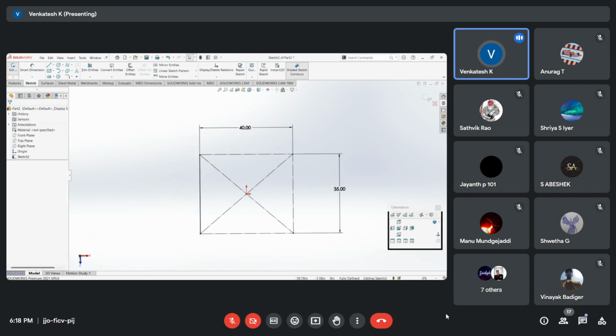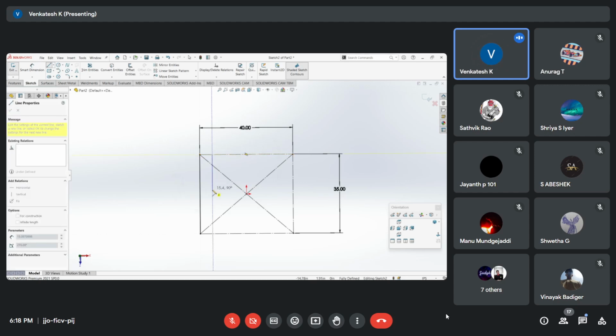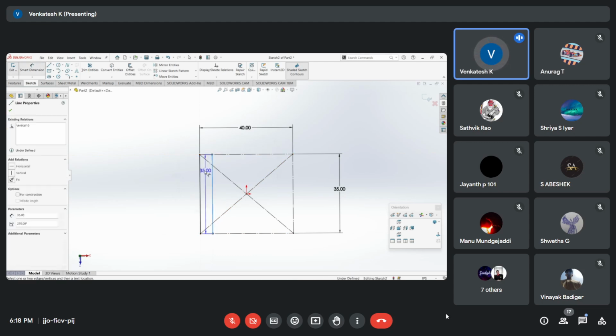Now the chassis won't include this. We don't include this in the chassis. We started just a bit before the rear axle to accommodate the motor and everything else: the firewall, battery, controller, everything, brakes. We'll start it from a distance of 8 inches.